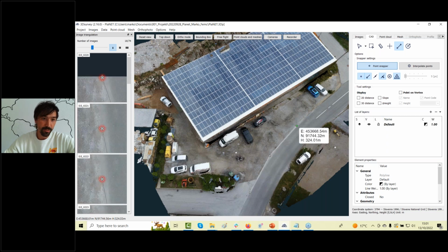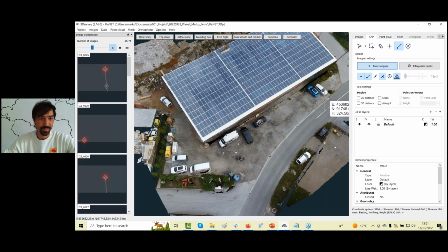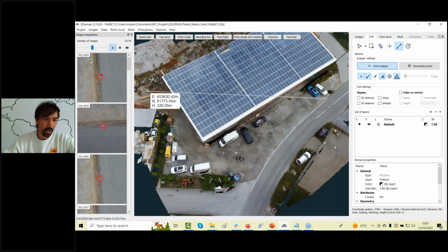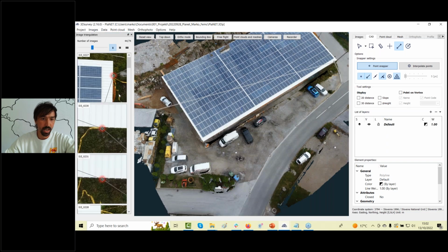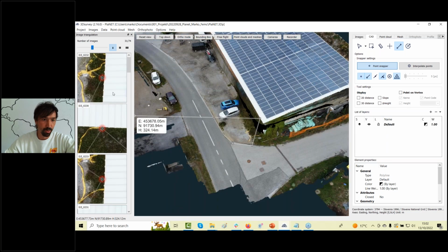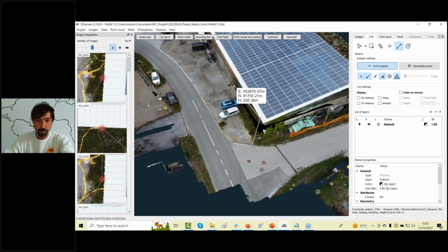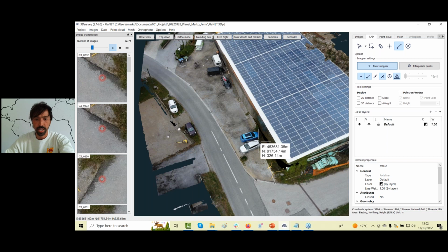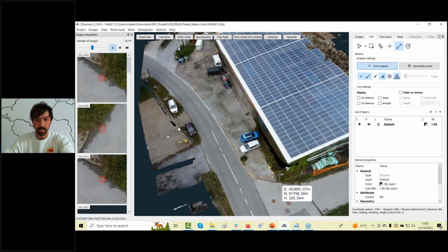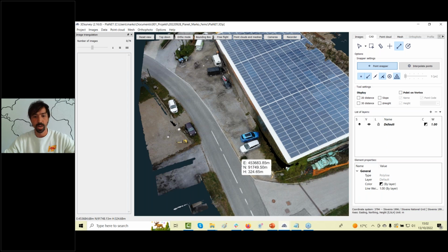But of course, you need to have version 2.16. In 2.15, this is not yet available. So this comes up, and when you close it down, then the small icon is here. It's kind of beeping to remind you, okay, you still have me available. And if you click back on this icon, you come back to the image support, and in this way you can help yourself. If you draw something incorrectly, like I did here, I snapped on the roof, just press backspace on your keyboard and you will delete the last point. So it's super quick.